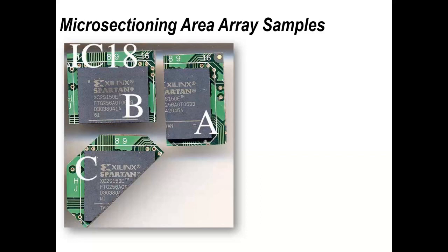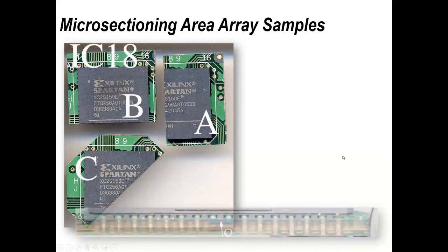Obviously, you're down to negotiation how much that might be. Another way of looking at it is doing a cross-section from the corners, as you see in sample C. That can be useful sometimes because you can see balls in different rows, but in one microsection. So it's more cost effective perhaps, but you can also measure the warpage, distortion of the package and board during the soldering operation possibly, and you can look for other facets of interest just with one hit. So it's more cost effective possibly, and you're getting more information for the expenditure. It's just a different technique, if you like.